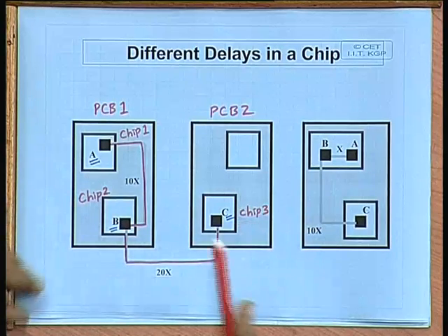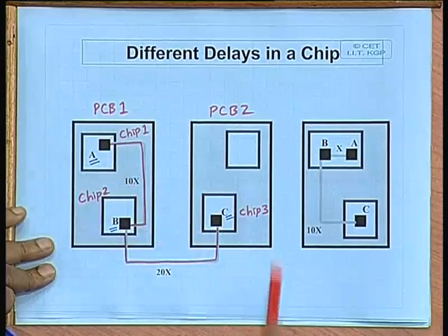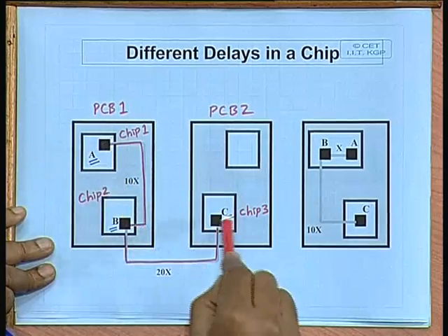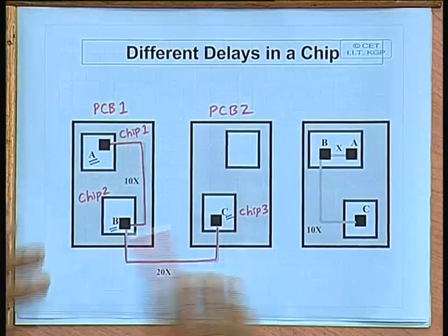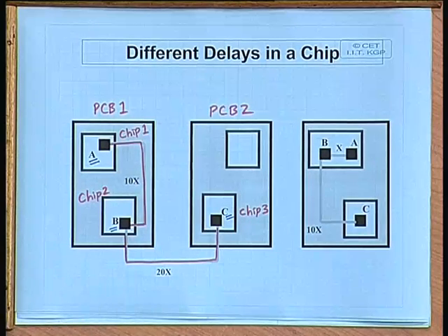So, in this solution, A, B and C, these 3 sub circuits get mapped into chip 1, chip 2 and chip 3. If it is a very big system, I will have to partition it into smaller subsystems, some of them can fit into a chip, some of the chips can fit into a board, and if it is even very big, it has to span across boards.